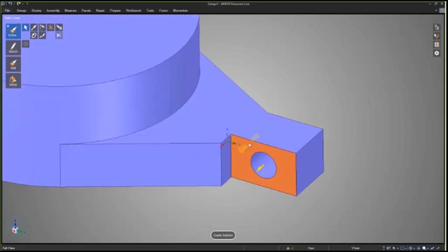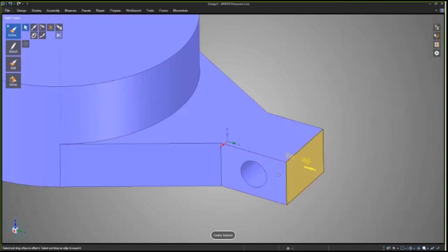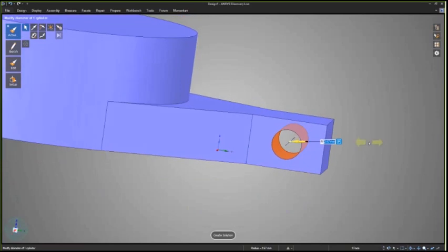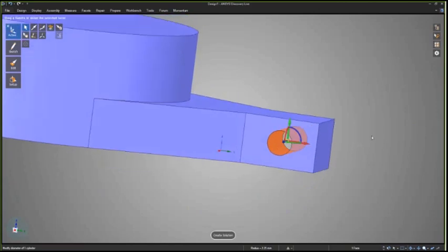Sometimes the best way to go back is to move forward. If I take this face here and pull it and snap it up to this edge over here, well, SpaceClaim doesn't remember that there was a cut there, so if I want to go ahead and edit it, it acts like it did before. So, moving forward with SpaceClaim is very easy. Sometimes you move forward to move back, changing the size of this hole, just like I did the pin earlier, or maybe it's in the wrong location.